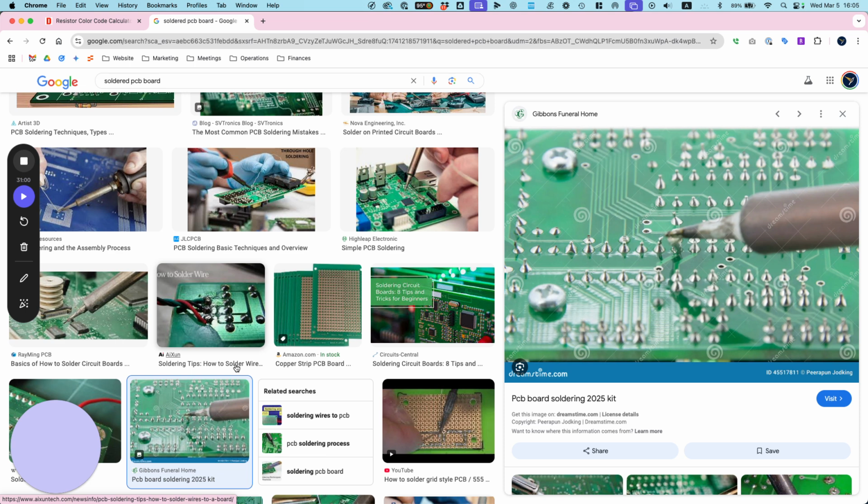I skipped row 15, so I'm on 16, and then I'm going to 14, just because physically I want to fit the LEDs. I'm physically blocked by the shape and size of this LED, so I can't really put it on 15. So I'm just skipping it for now. I could have put this on C10, C5, whatever. All the C's are still connected. I'm just keeping the LEDs close to each other. So for now, that will work.